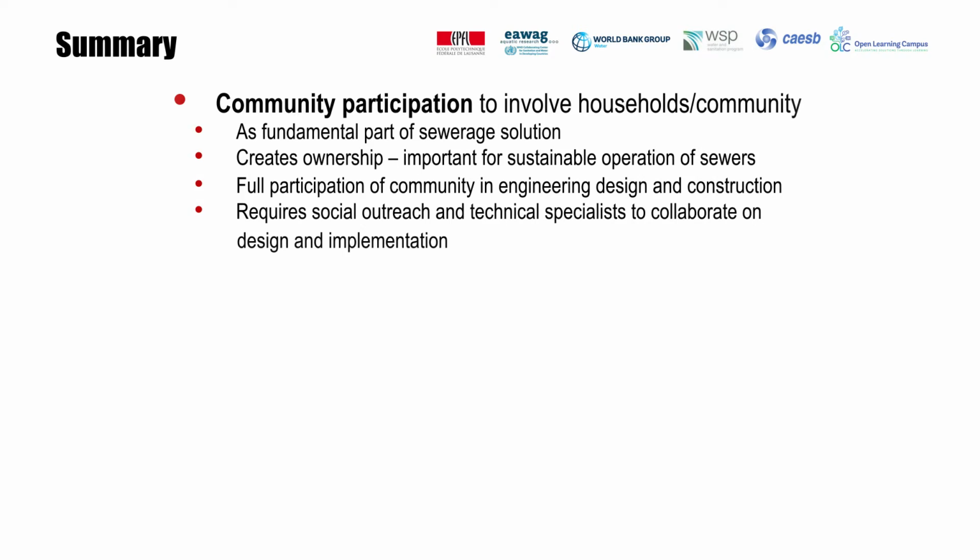The condominial approach involves the targeted households and their community as a fundamental part of the sewerage solution and thus creates ownership among the users, which is an important factor in the sustainable operation of the sewers. The condominial approach is based upon the full participation of the community in the engineering design and construction of the local sewerage system. This requires that the utility employs social outreach specialists as well as technical engineering specialists to work in conjunction on the design and implementation phases.